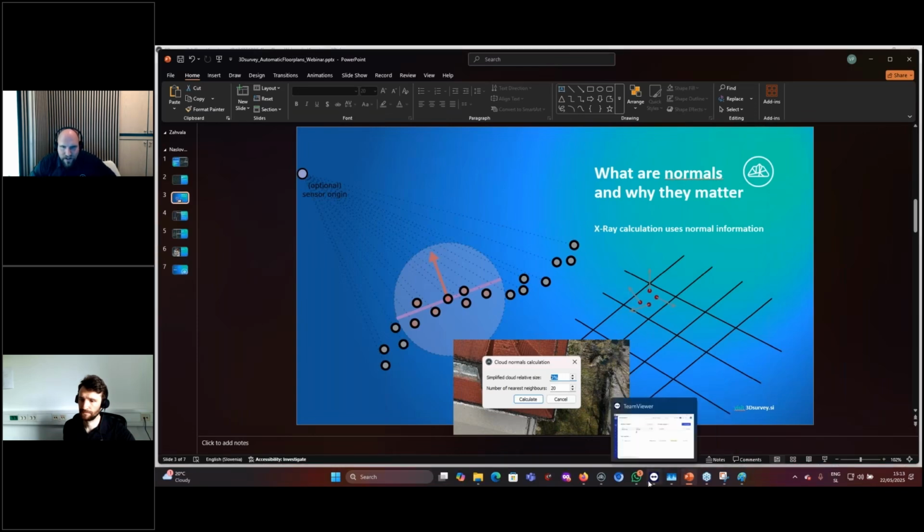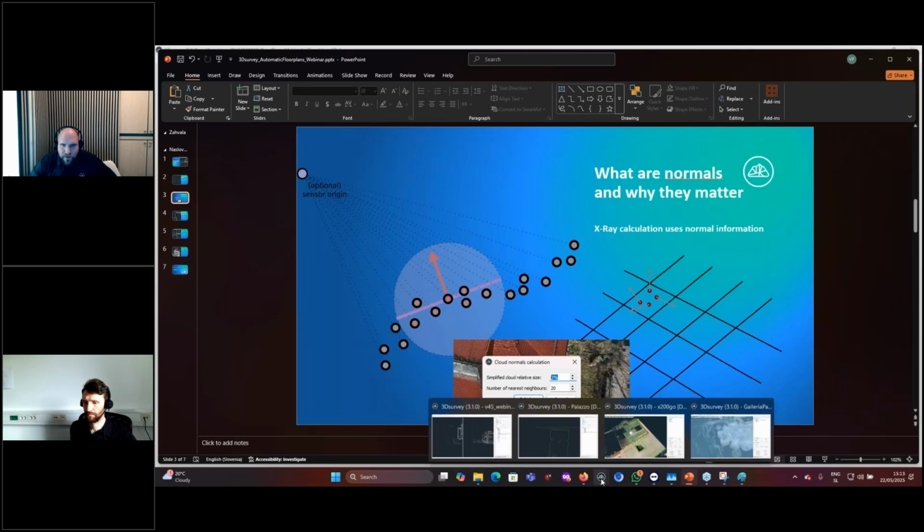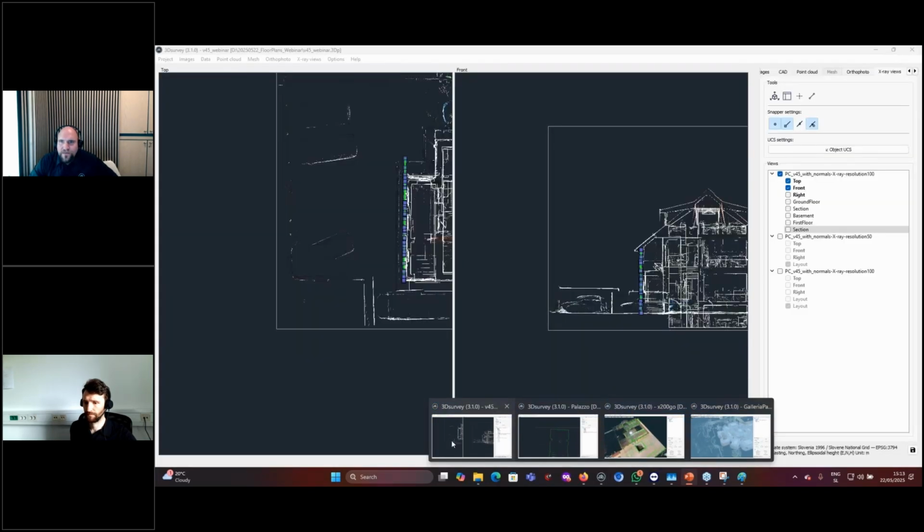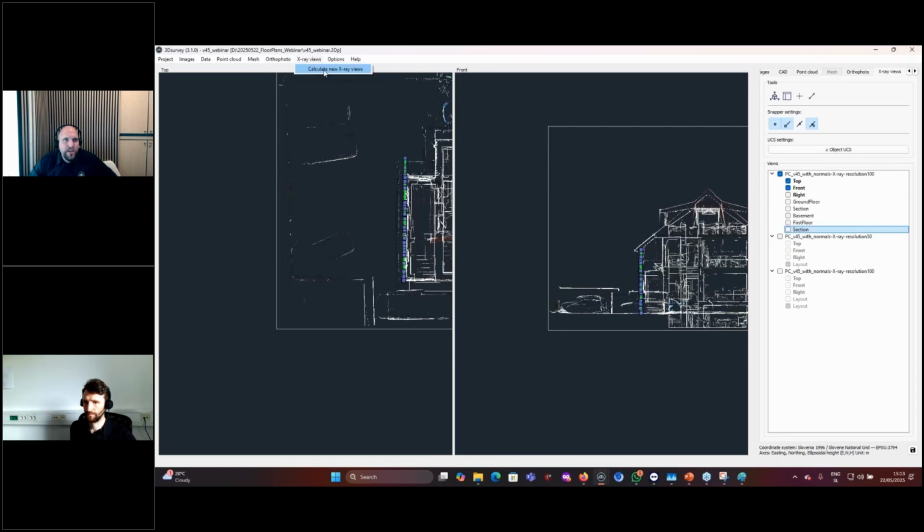So if you set a very high transparency parameter, for example 99%, then the opacity, that's 1 minus transparency, is 1%. That means that 100 points will need to fall into that point in order for it to be white. We can try it, for example, to play around here. We can go to X-ray views, create new X-ray views. We'll just use all, put it the way we have it, 1, 99 here, press generate.